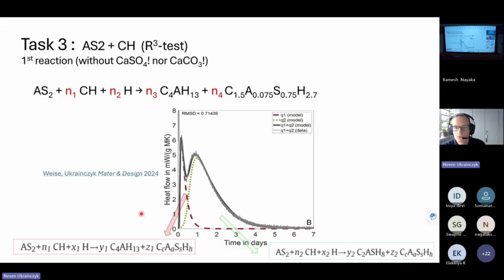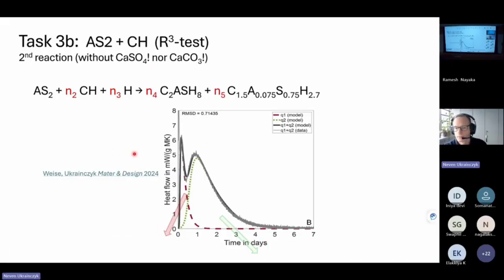So now you know how to solve these equations. These are the papers from Zunino and Scrivener group. But I saw from Zunino that he didn't do the balancing correctly, which was okay because it's only approximate. But now you can do the correct stoichiometry and do the correct reactions with carbonates. So this is also the second reaction you can solve. This can be your homework task. But basically it's the same approach as what we just did, and you can practice on this one.